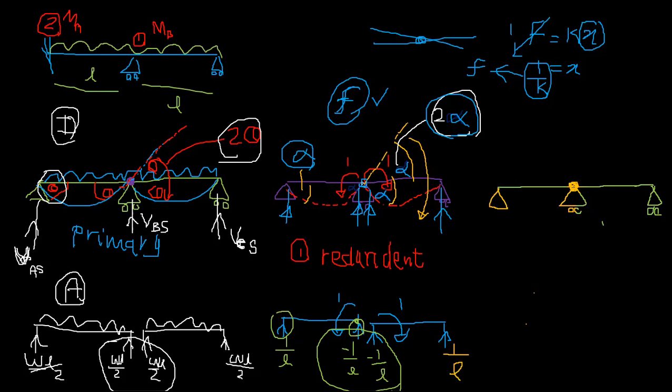So you remove the MB, but you are giving a unit bending moment 1. So actually you have to multiply everything finally by the original MB value, right? These displacements are for a unit force. So how much it would be actually for MB, right? That's what you have to do.